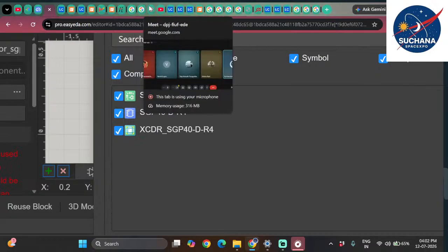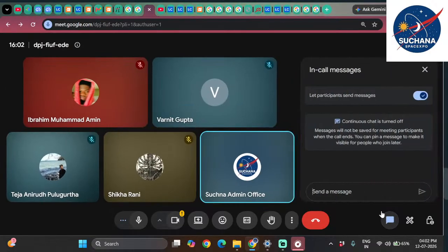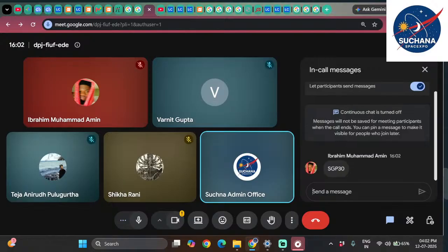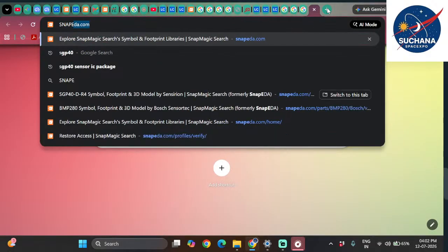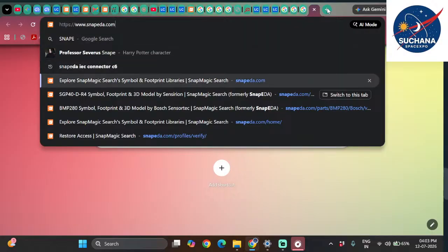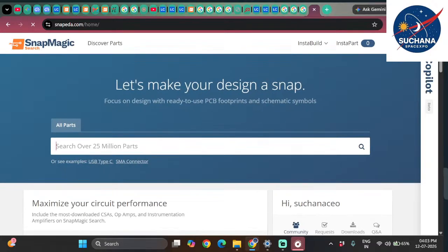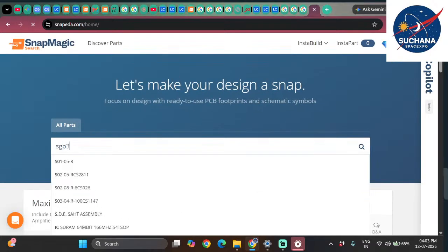So you said SGP30, right? Is it 30 or 40? Can you post a message in the chat box? Is it SGP30 or 40? SGP30. Okay, so for SGP30, first you need to go to snapeda.com. Then here you can search for SGP30.